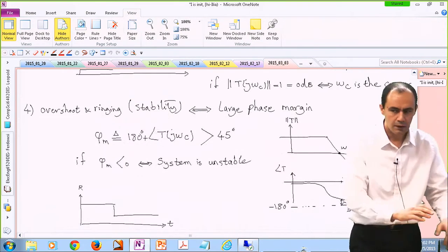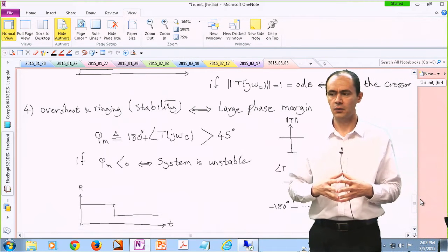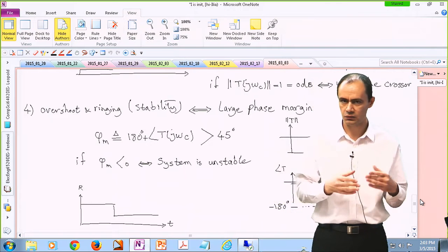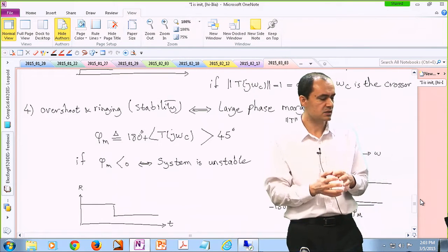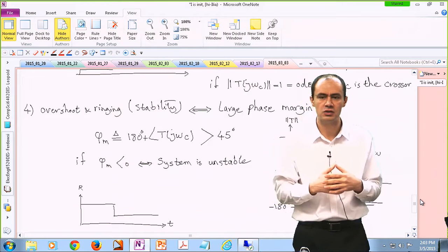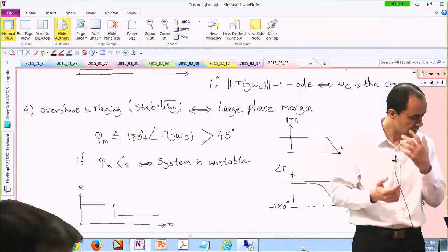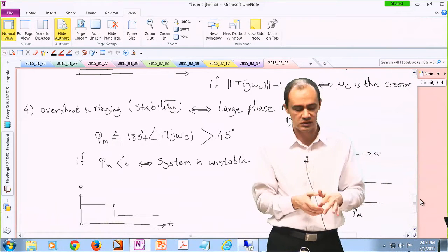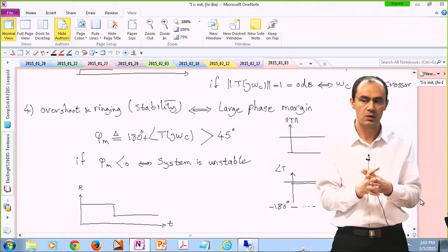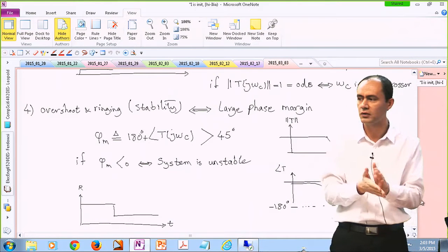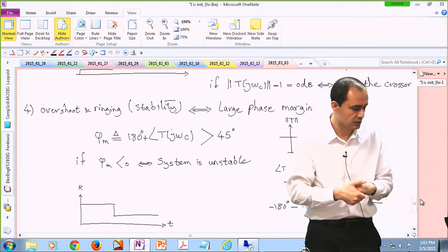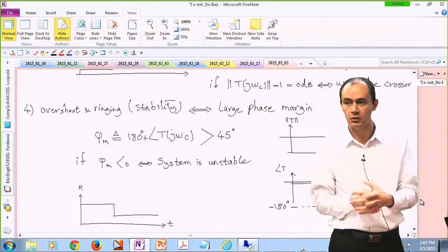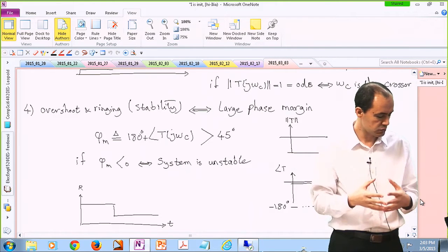And also, the very basic expectation that we have from our loop gain is to make sure that it is actually stable. How do we measure or quantify stability? We look at the phase margin. If the phase margin is positive, the system is stable. In order to be really sure and the system be deep into stability, we sometimes say the phase margin should be more than 30 degrees or 45 degrees or 60 degrees or something like that. If you are curious about what phase margin is, we look at the Bode plots of our loop gain, the magnitude and angle.